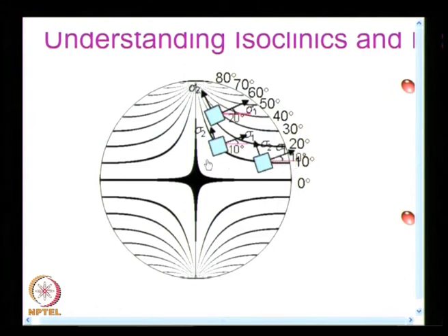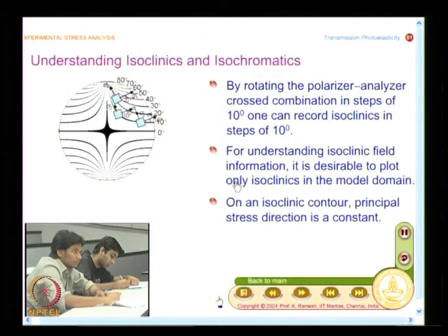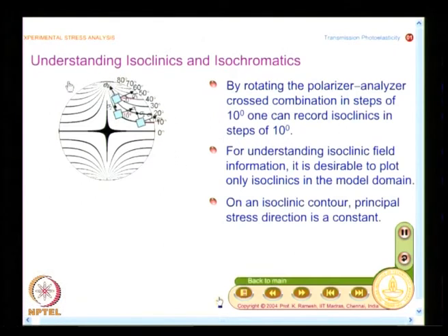That will give a very interesting result. Take that as a home exercise. So, what you have as isoclinic is a little subtle, and to get plots of this nature, I need to conduct a series of experiments and record them carefully in a conventional photoelastic analysis.